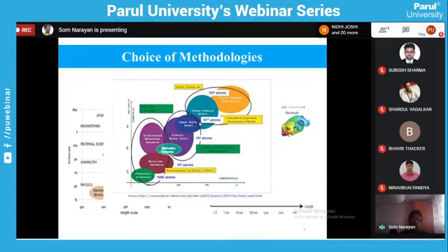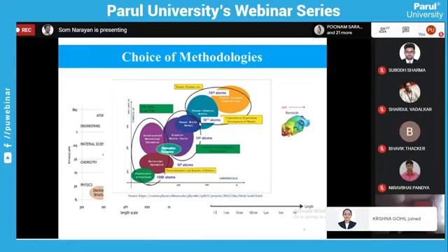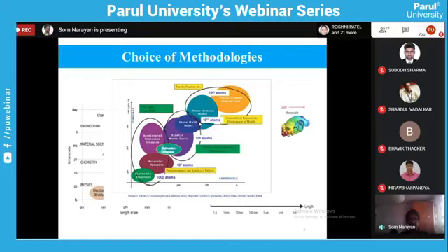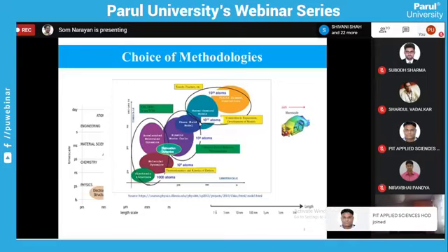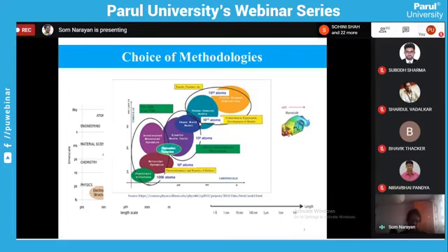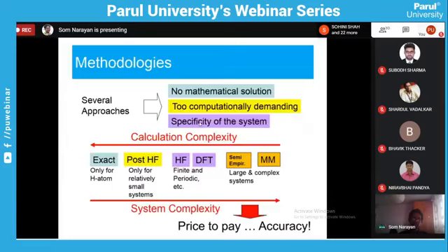So over here it is the summarization. If we go for 1,000 atoms, we can do electronic structure, molecular dynamics, then accelerated molecular dynamics and dissolution. And that falls basically in physics, chemistry, and material science. As we go for engineering systems, that is more than 10^8 atoms, then we go for kinetic Monte Carlo or phase field models. Or if we go beyond 10^23 atoms, then finite element simulation is better. So in a nutshell, we can summarize like this.